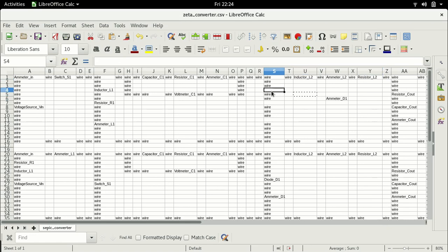And the diode comes in the parallel path. So this is a ZETA converter, the one above, right? Now, let's try to figure out what's going to happen. We already said when the switch is turned on, the voltage source charges the inductor in the clockwise direction, right? But at the same time, when the switch is turned on, this is really a parallel circuit.